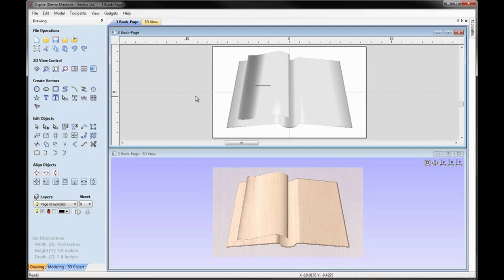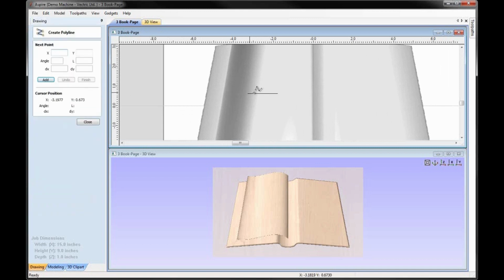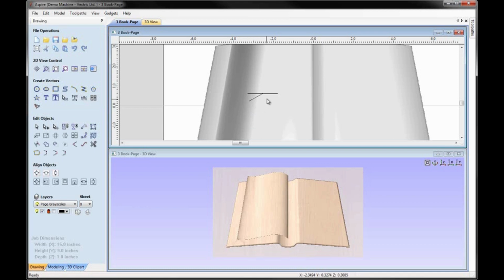So if I zoom in a little, choose the option to draw polyline, I'm going to snap to the midpoint of that line, and then I'm going to come down here and we'll go length 0.8, angle 30. You can see the values being displayed on the screen there. Click and then right mouse click to close that. I'm going to select the line and delete that. It was just there for construction.